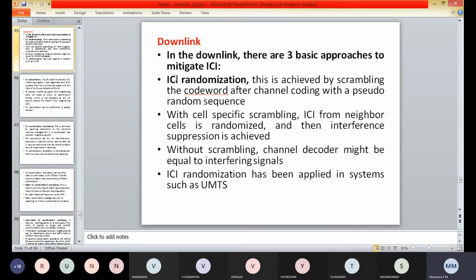Here, linear spatial suppression using statistical knowledge of the interference channel is a practical option for intercell interference cancellation, but its application in the downlink is limited by the capability and the number of antennas at the user equipments.